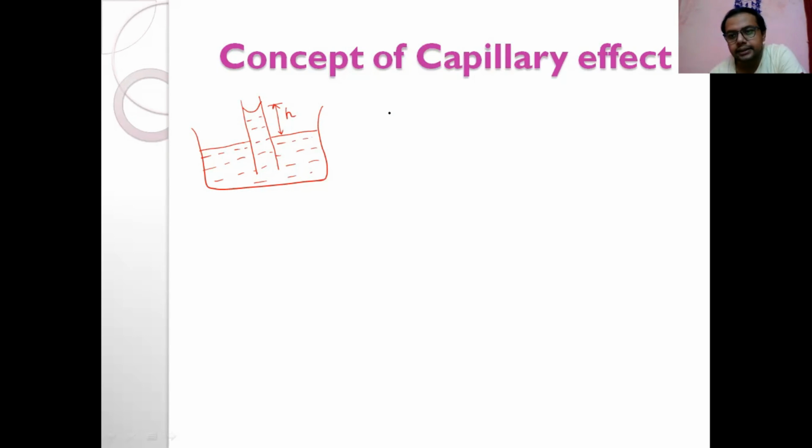And in this case, just to remember from the previous lecture a few hours back, you have seen the equilibrium equation: delta P is sigma into (1/R1 plus 1/R2). So here, if I magnify this portion, the tube, I have made it like this.